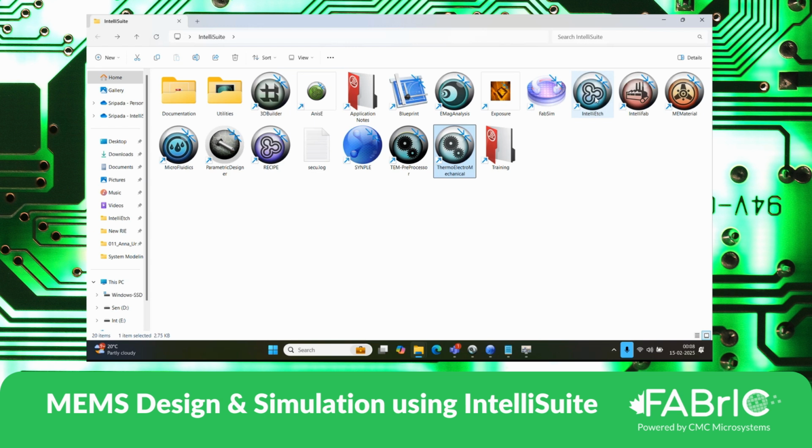And we also moved on to a module called IntelliEtch, where we do a dedicated wet etching simulation of silicon and quartz by user-defined orientation. That's the novelty of this module, where we are not doing simulation only for standard plane orientations. It's a user-defined orientation, like 201, 234. So it's purely a physics-driven simulation output, which is validated with experimental data.